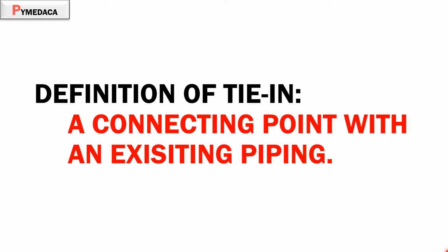Okay, the tie-in location, it's nothing but, you have to understand the definition of tie-in. So what is tie-in basically? It's as simple as that: a connecting point with an existing piping. For example, if there is an existing piping and you're going to take some tapping, that tapping is a tie-in point. The tie-in point may be 1 or it may be 2. Basically, the tie-in point is a connection between your new piping and an existing piping.